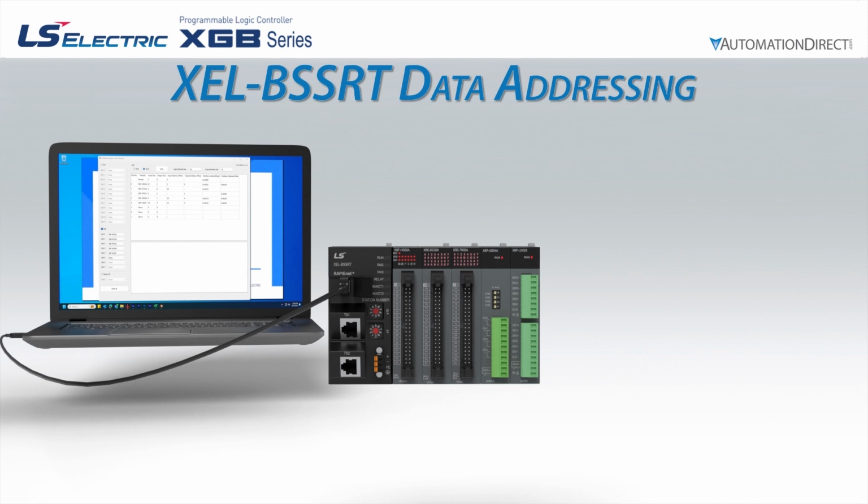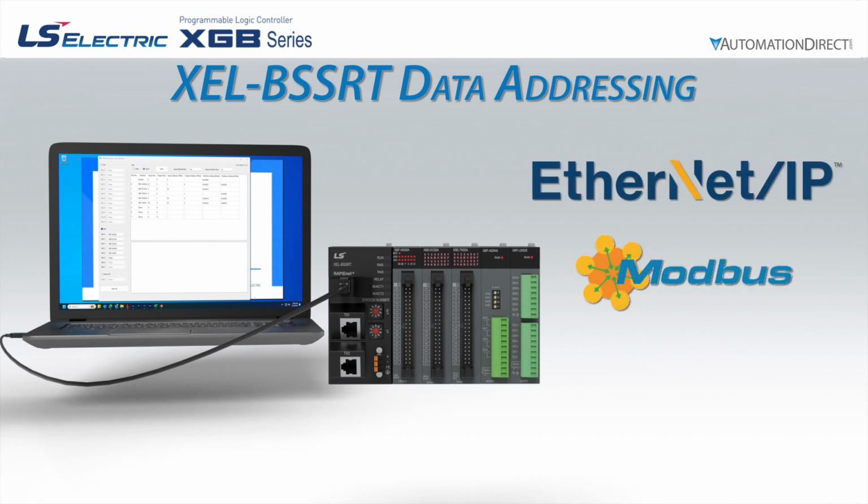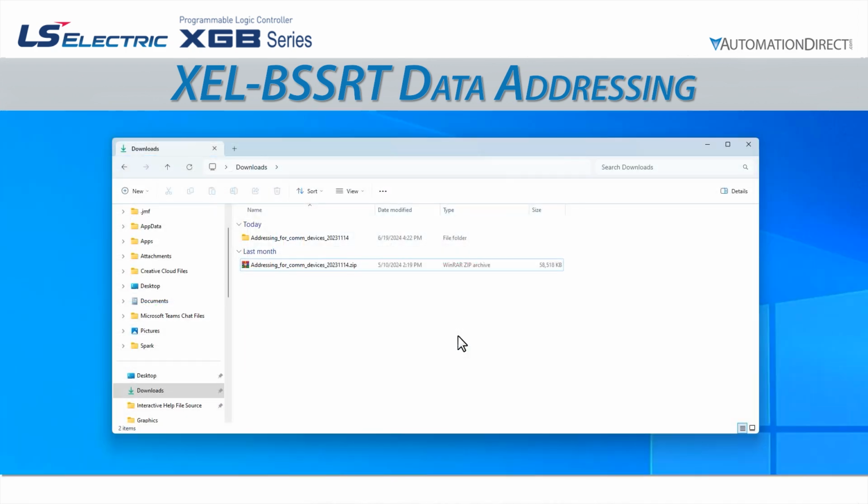The BSSRT addresses data locations similarly for Ethernet IP and Modbus TCP. Both protocols use the same data addressing software and have similar data offsets, so this information will work with both protocols. We will start by downloading the data addressing tool. This software is called Addressing for Communication Devices and is available to download from AutomationDirect.com.